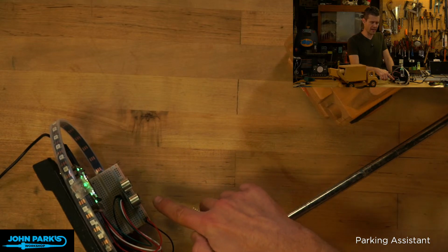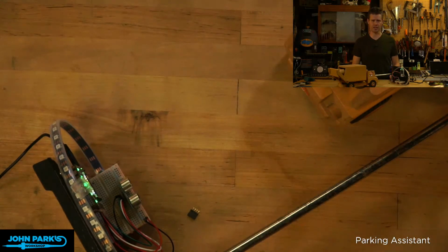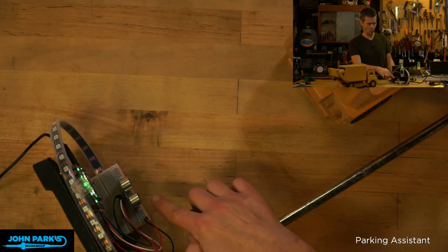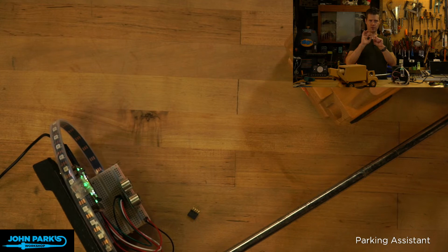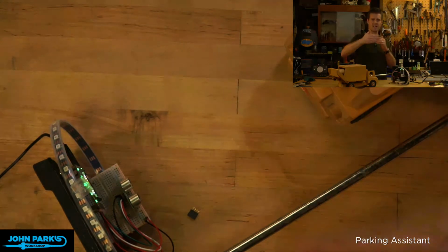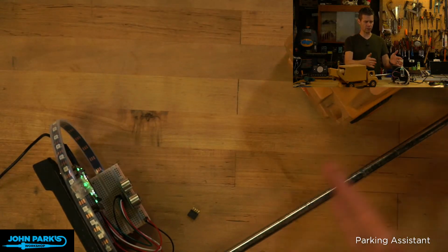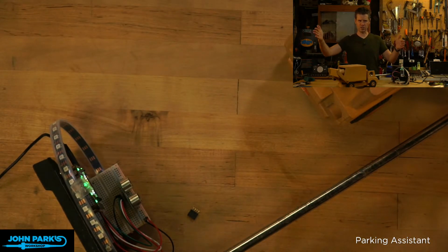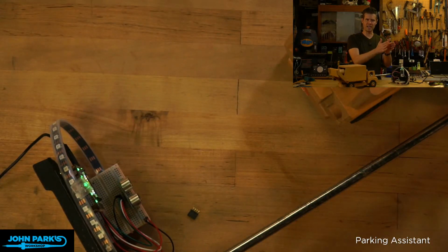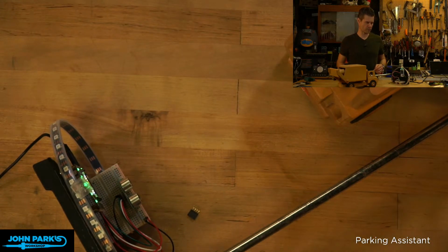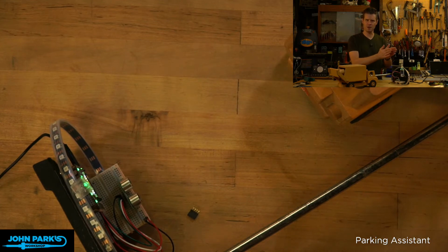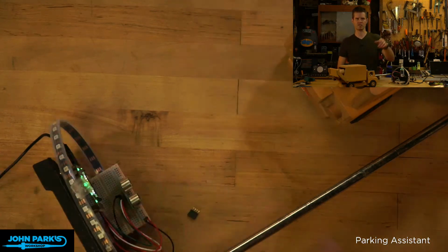And I have an ultrasonic sensor, and the ultrasonic sensor is essentially like sonar. The idea is there are two little elements there. One sends out a ping, a high-pitched frequency ping, and the other waits to hear that reflected sound, and it essentially counts the time. How long does it take for that echo to go and come back? With this, you can estimate distance, and this one is particularly good for distances of about a couple of feet down to an inch or so. So I think maybe up to 3 centimeters, something like that. I'll check the specs and I'll show you that in a second.